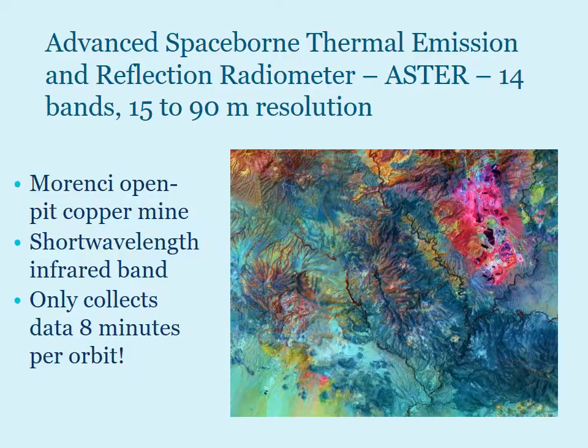Another one is ASTER. It's got 14 bands that it uses, and it's got pretty good resolution, 15 to 90 meter resolutions. But unlike MODIS, it's not collected every 2 days. It's collected only 8 minutes per pass, and it can be focused on various areas. So this happens to be Morenci copper mine, but it is pretty interesting geologically, and of course it doesn't have good repeat.